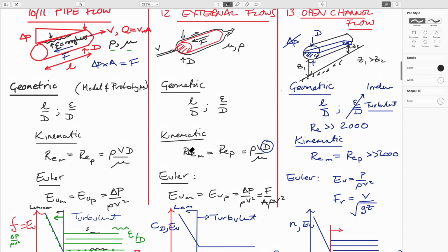And if we know what that flow is, we can usually index that relative to an Euler number, which says, in this case, what is the stagnation pressure on the tip of this thing? Really, the difference between the pressure on this side and the pressure on the back side is the force that's applied to keep it static in place. We're interested in the force applied on the structure here, and the force applied on the fluid here, but really they're the same thing.